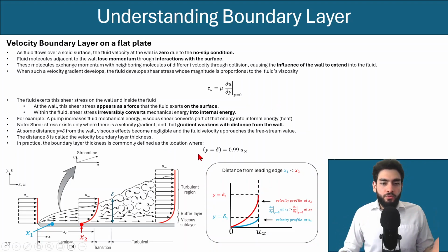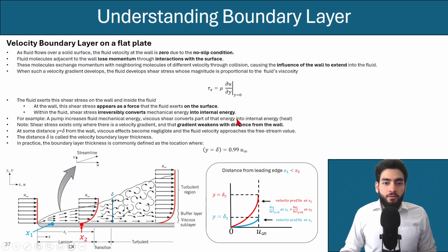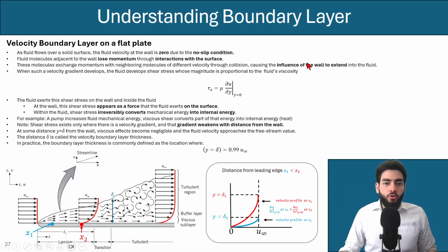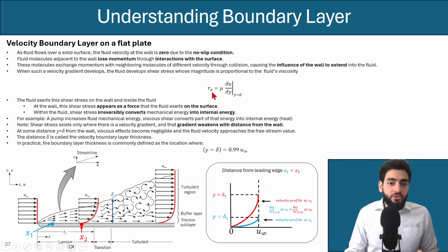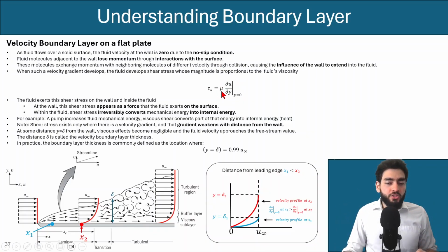Also, I want you to note that with the case of this flat plate, the velocity gradient decreases and weakens with distance from the wall. So the more you travel in the x direction, the more that this velocity gradient will start going down. And so maybe one thing you start realizing right away is that this shear stress changes as you travel along this plate. And so the more appropriate term to use is local shear stress.